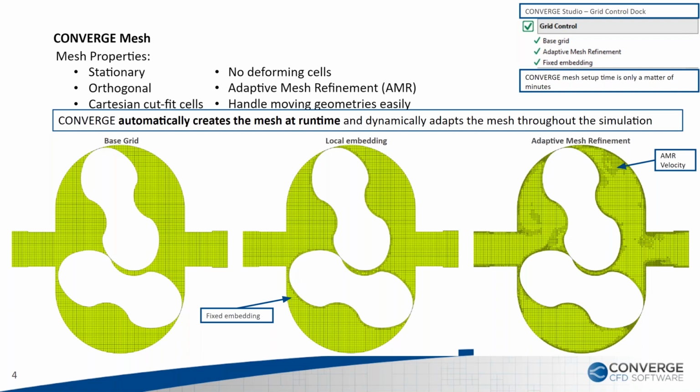We allow you to specify whether you want to refine the mesh spatially or near some walls or some other boundaries. But we also have a feature called adaptive mesh refinement. And this is a really powerful tool for accelerating your CFD simulations because it allows the solver to automatically add and remove mesh refinement where there are actually flow features that you want to capture. So we have a lot of different parameters you can set in order to tune your AMR to really capture just the important features in your simulation so that you don't add more mesh if you don't need it.